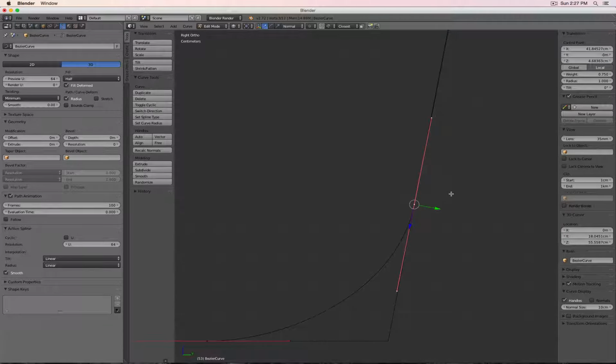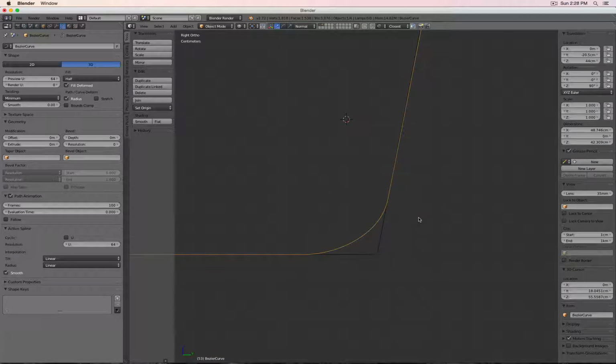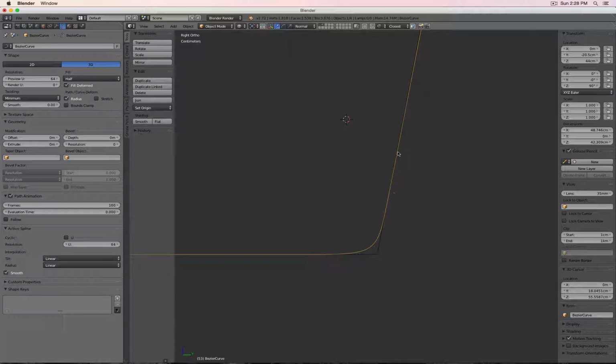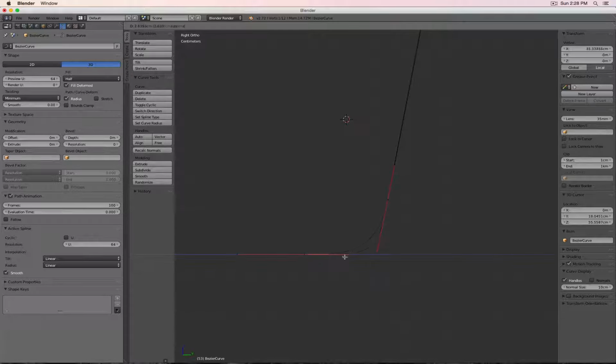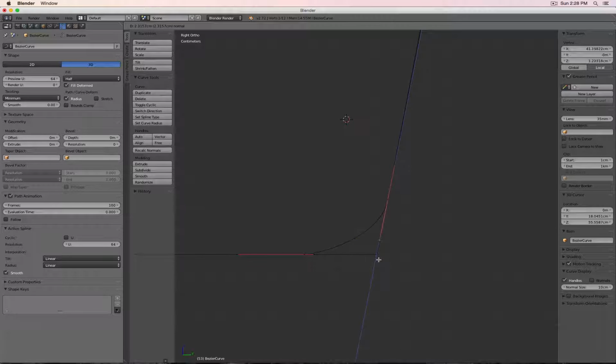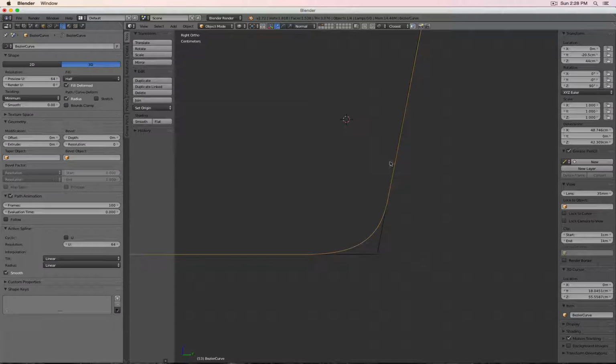So I have a little bit more local control over my edge rounding, and then I can push those handles nicely out, for example, to have a much better transition. See, when I make this one really small and move this one up, you see how flattened this curve gets. So there I can now nicely sculpt that shape and transition I'm looking for.